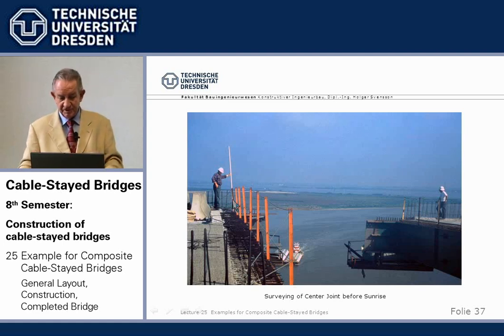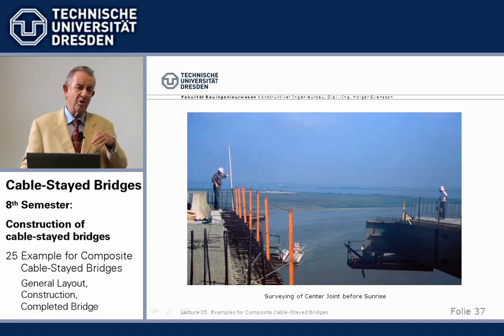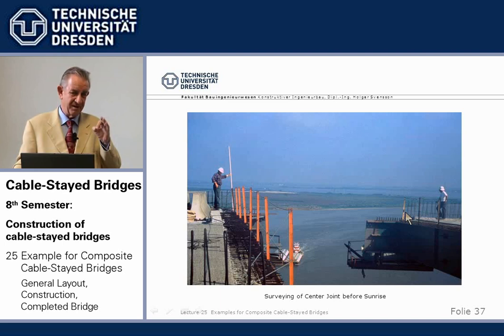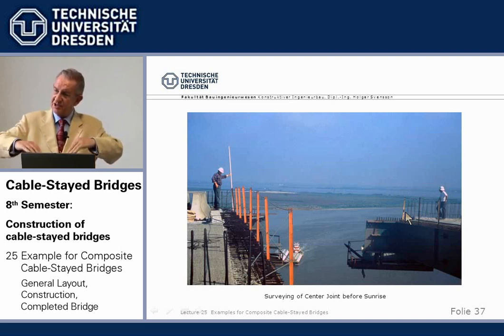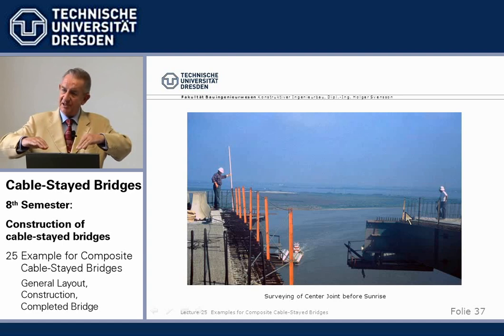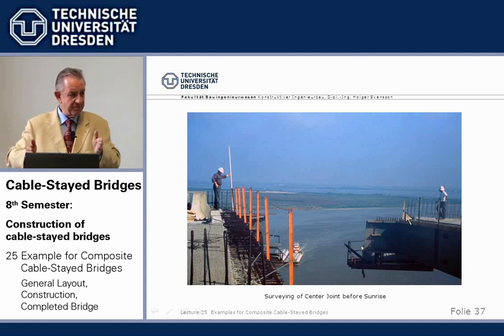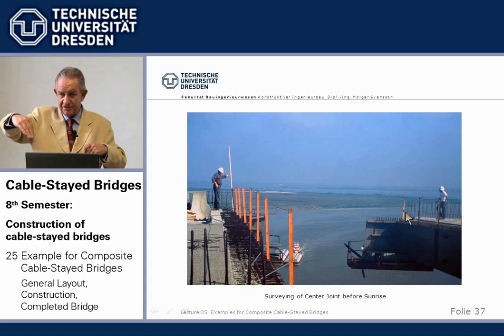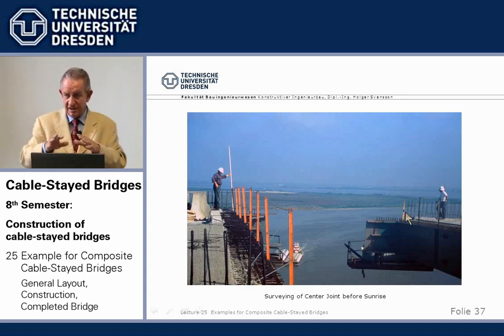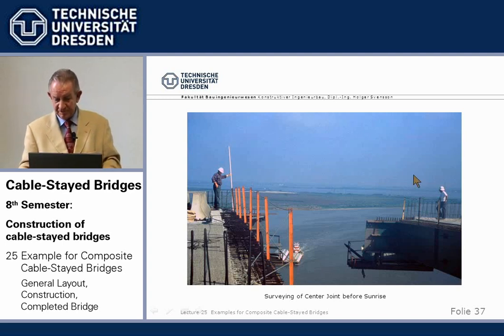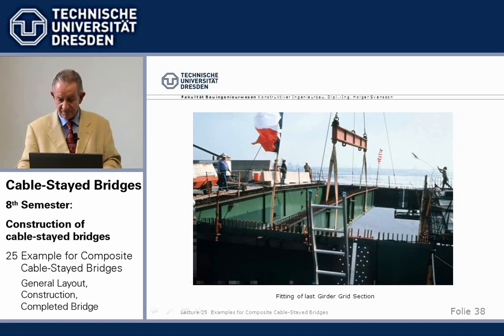So you have to survey very carefully, and you do that always very early in the morning, just before sunrise. Because then, especially in Texas with the hot sun, the non-uniform distribution of temperature from the sun hot on the deck is evened out as well as possible. And here we lift up, flying the flag, of course the Texan flag, the last piece.